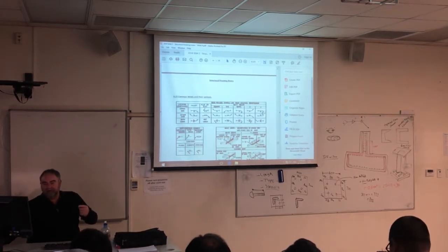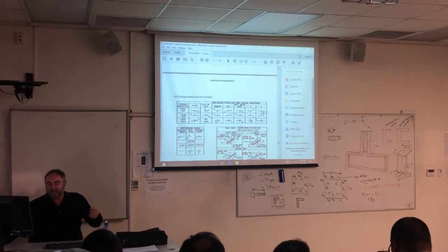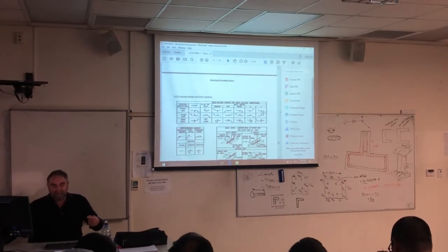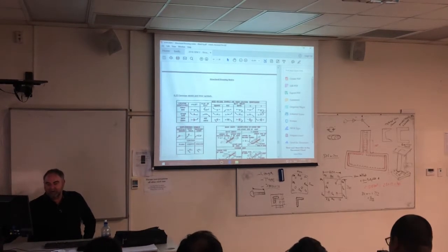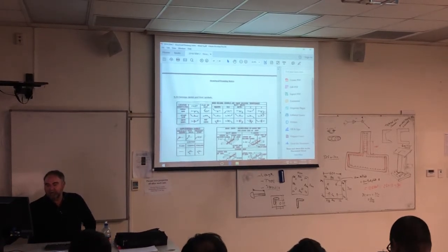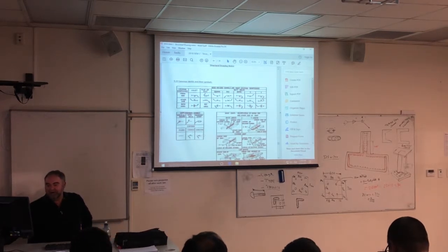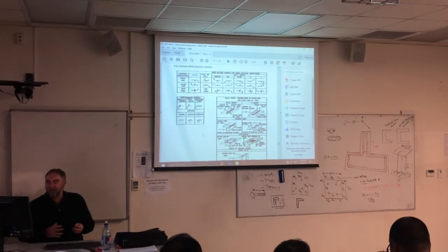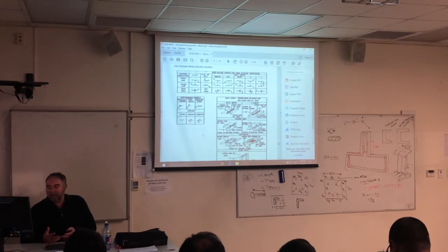If it's pointed up, it means the weld is on the other side of the arrow, and if it's like this, it means the weld is on both sides to the arrow. There's your side weld and your round weld. And there are some little wee diagrams here which are quite cute, and they do show you exactly what the weld is and what the symbol is for that type of weld.